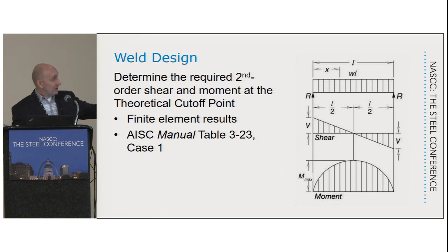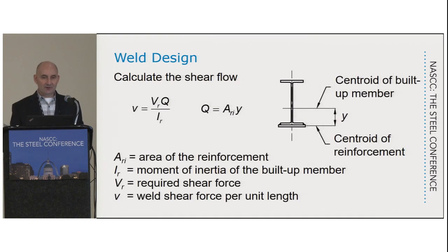And in this case, here's our notional load up here. We're going to have a theoretical cutoff point somewhere over here. So our shear is going to be somewhere in that range, and our moment's going to be down here. But typically, these loads are so small that on a real project I just calculate based on the maximum shear and moment. If I were going to do it for a presentation, I would probably go ahead and do the full calculation, but the loads just aren't big enough to worry about unless you have a giant high-rise building.